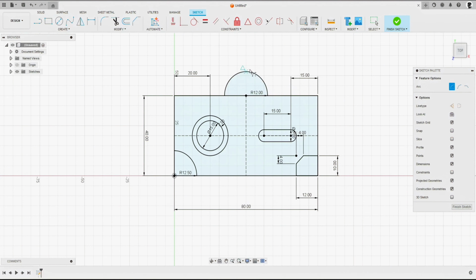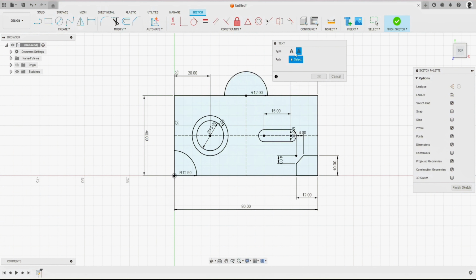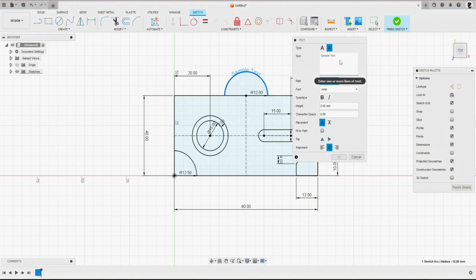Now we just need to add the text on top. On the creation tools, let's go on text. But in this case, we don't want the text box, but rather the text on path. Now we need to identify the path. In this case, it's the arc. And in terms of the text, we've got Fusion 2025. Okay, I might bump that size up a bit. Let's go for 2.5. Then we want to make sure the alignment is in the center, not offset like so. And that's the correct orientation, horizontal, not vertical flip.